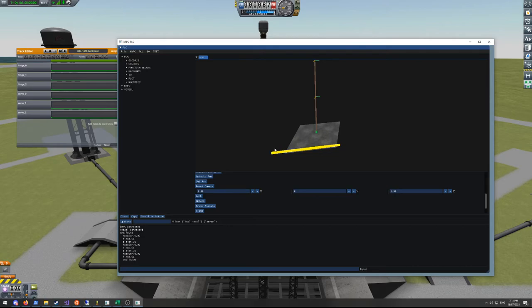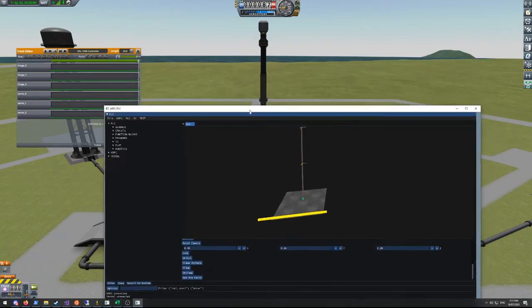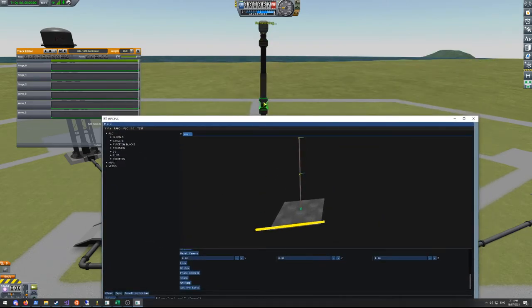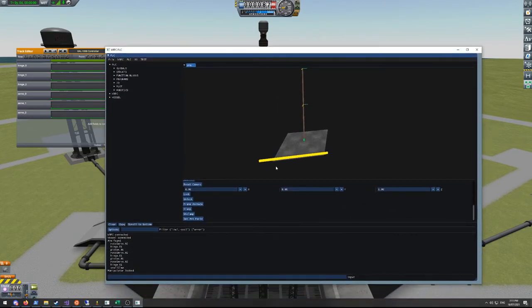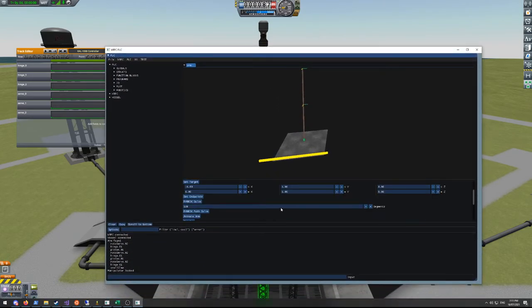So it's going to stay flat through the whole path. So we'll lock that. Clamp just clamps the rotation angles so that the hinges don't go past 90, because they can't go past 90, so the values that we calculate won't go past that. And then we will do a path solve.